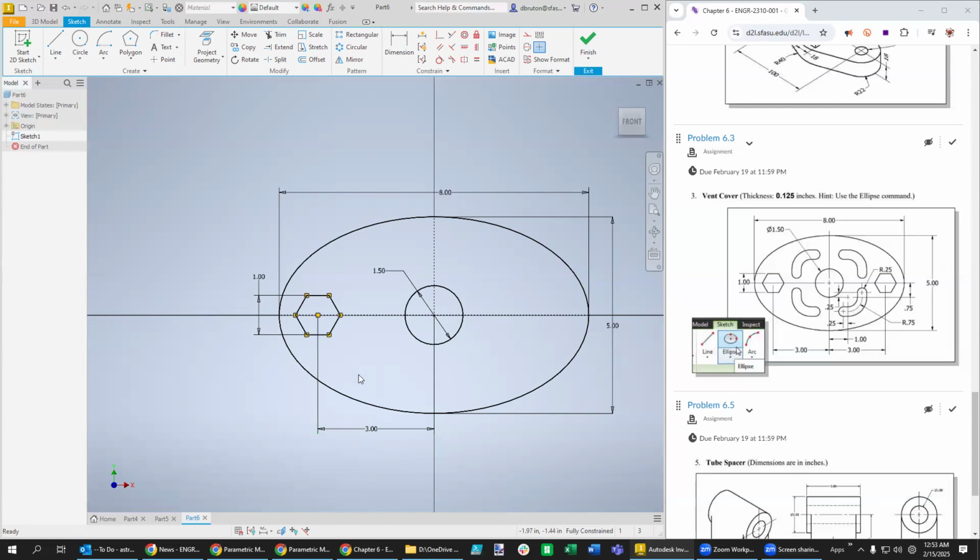At this point, we could go ahead and make a symmetry mirror object of these. The object we want to select is this one. I wonder if we select there, will it do it? I don't know. Looks like you've got to do each of those lines, which is unfortunate. Maybe another way to do it is to select them using the click and drag approach. So like this, and then say that we want to mirror this about the vertical line. And then we want to apply it. And now we have the identical shape over there.